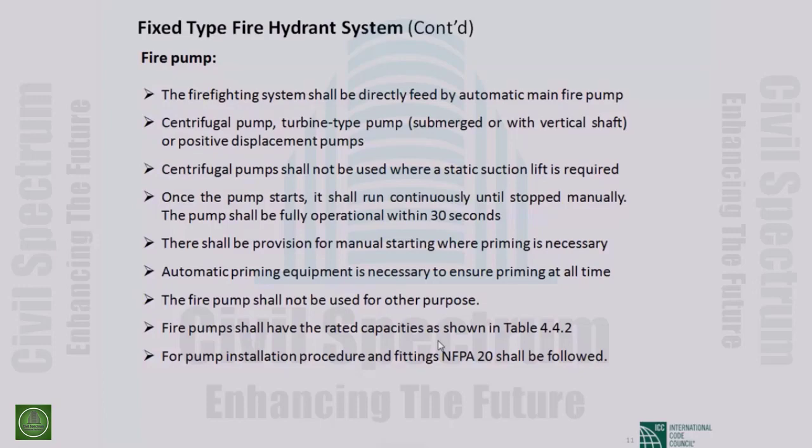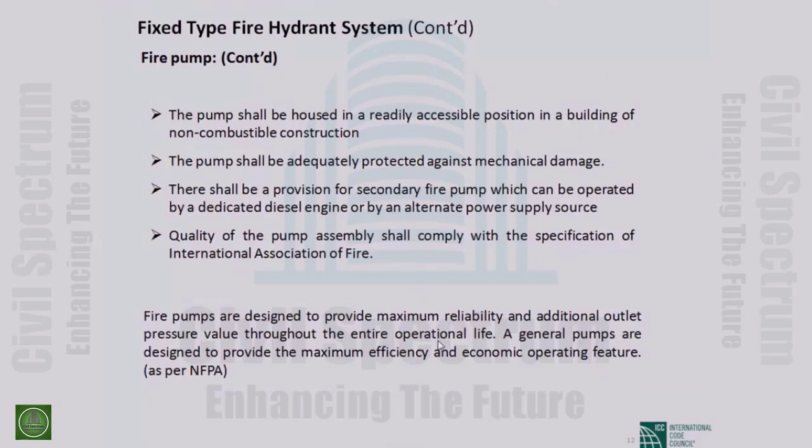Actually, in a hydrant system, the fire pump is a very critical thing. So you have to be very careful about the pump and its capacity and flow capacity. The pump shall be housed in a readily accessible position in a building of non-combustible construction. Normally, the building of the firefighting pump is one-hour fire protected. The pump shall be adequately protected against mechanical damage.